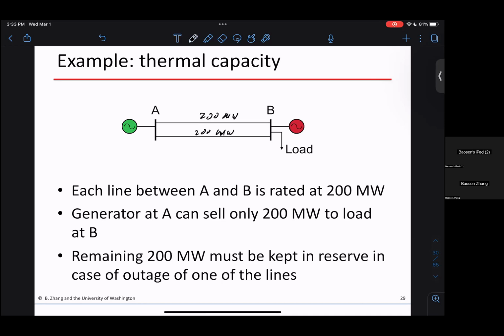So what is the set of possible contingencies here? Well, the set of possible contingencies is this generator fails, that generator fails, both of the lines fail, right? If you consider all of them, then this problem is not solvable, right? So all bad things can happen, and if every generator can fail, then there's nothing that can supply the load. Okay, so typically what's considered here, the critical contingency, is not both lines fail, but one of the lines will fail. We consider that to be critical. That's something that can reasonably happen.